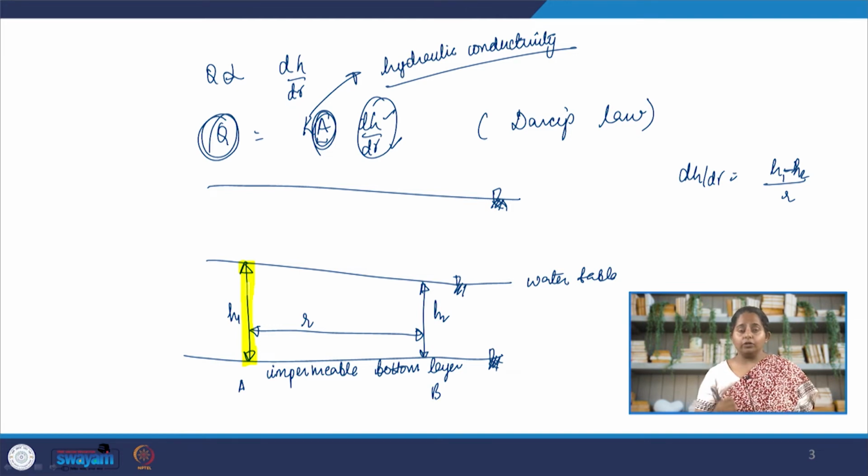Now in this case, we want to understand how the contaminant is flowing along with groundwater. Now remember, groundwater is flowing in this direction from higher pressure head towards lower pressure head. Intuitively, we know that the contaminant will be transported in the direction of groundwater. Now, if you remember our air pollution model, the Gaussian plume model, the contaminants were transported downwind in the direction of wind. Here, instead of wind, we have the flow of groundwater. Now, if we make a few assumptions, the first assumption is that the contaminant is undergoing plug flow.